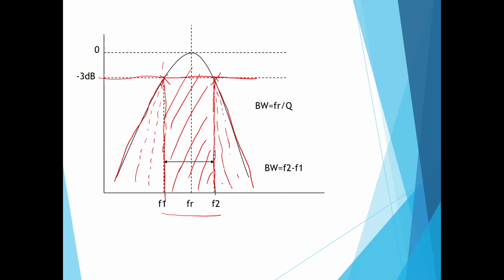Because we can remove the other frequencies. If you see from this frequency response curve, minus 60 dB is somewhere over here. It crosses at this point and at this point. This is minus 60 dB.